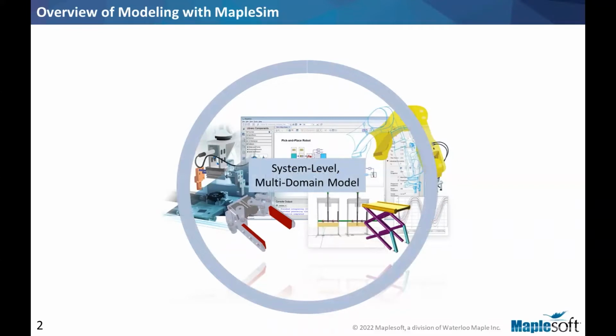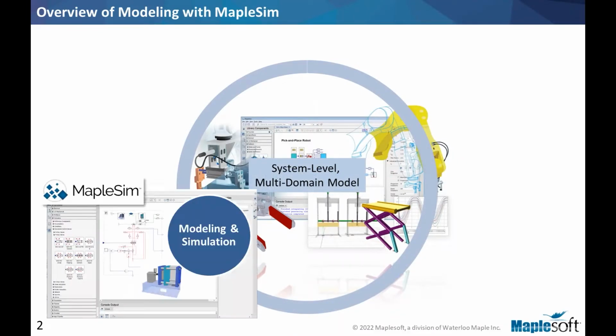It is a system-level multi-domain modeling tool. So what this means is we're not looking at so high level that you don't have any real physics embedded within, and not so low level, not on the level of say an FEA or CFD. We're kind of in the middle, multi-domain, because we can obviously mix different domains: mechanical, electrical, hydraulics. And we're going to see an example of that in today's webinar, where we actually have a hydraulic system, but there are also some 1D mechanical pieces involved as well.